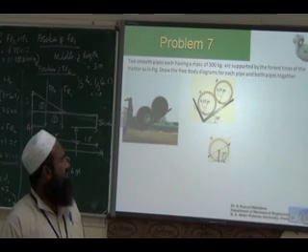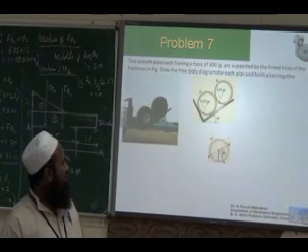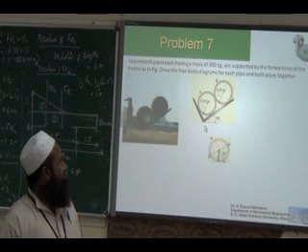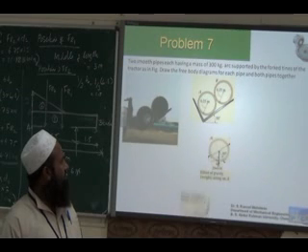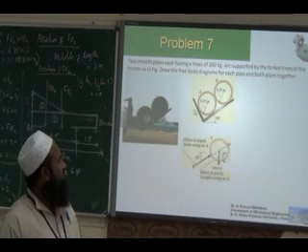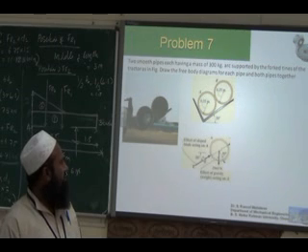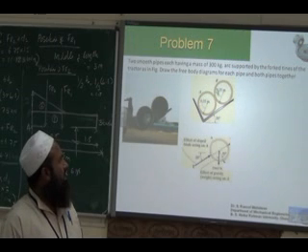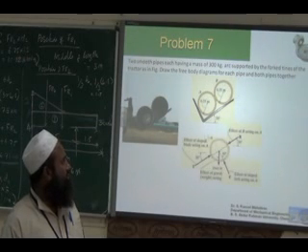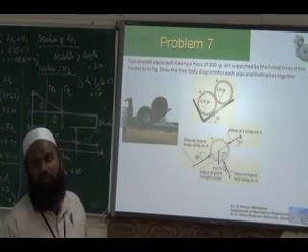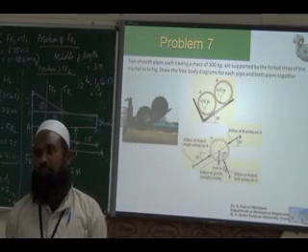If you consider the first roller, it will have the load, the weight of the roller, effect of gravity, then restriction from this surface, perpendicular to this surface, one reaction, then another roller B will produce another reaction. So we have three reactive forces and also weight. There is no moment, it is free to rotate.